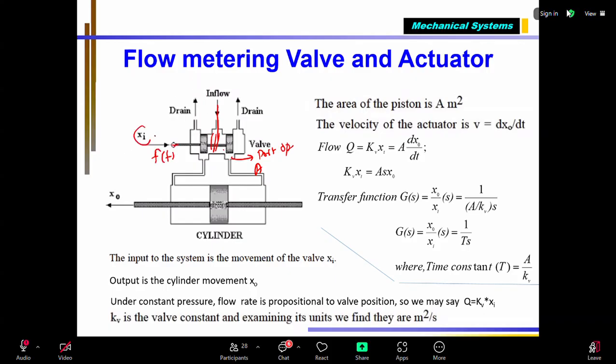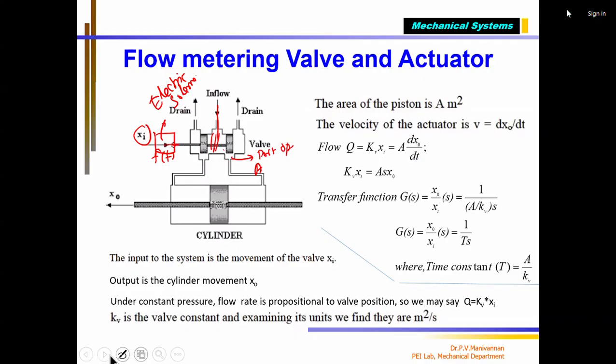When I give electrical power to the solenoid, it generates a magnetic field which pushes the solenoid stem. The stem is attached so that the spool valve moves. When I give the displacement like this, the spool becomes like this. You can see the new position of my spool.